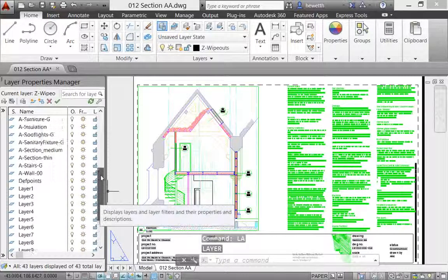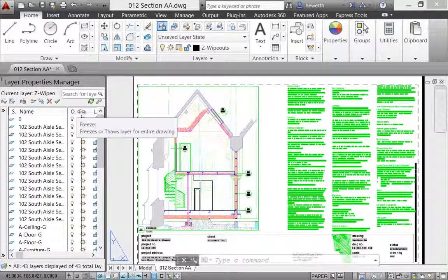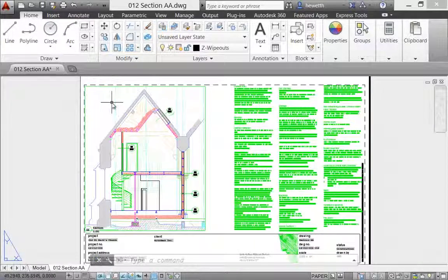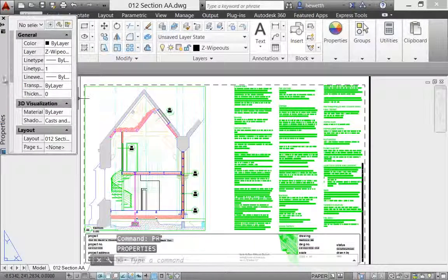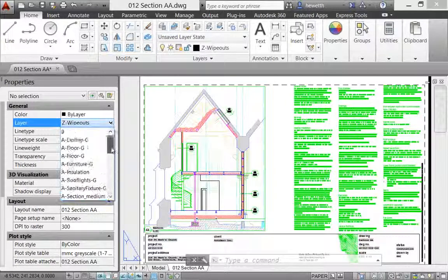And you can see here, if I scroll up to where the Xref files are, or Xref layers, you can see that I've got all these layers coming in from this Xref. Now, if I look at the Properties window, let's go ahead and open that and display the properties for this drawing. Notice that all those layers that come from that Xref are not displayed in the Properties window. That's because they're with an Xref and you can't really modify them.